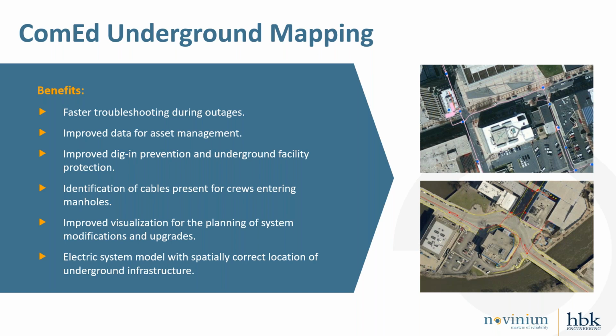An underground installation maintenance crew could go look at the updated mapping system and manhole assessment information to understand where the cable system existed within the manhole, what ducts it occupied, and what else existed in the manhole. Prior to this, they had antiquated maps that may have inaccurately depicted 2 circuits in a duct and manhole system, when in reality there were 7 circuits going through the system. In short, this allows everyone to better plan their work. From our engineering standpoint, as designers, the visualization aspect with spatially accurate locations allows for better design decisions when it comes to impacts to existing underground infrastructure, the public, installation hurdles, and things such as traffic control.